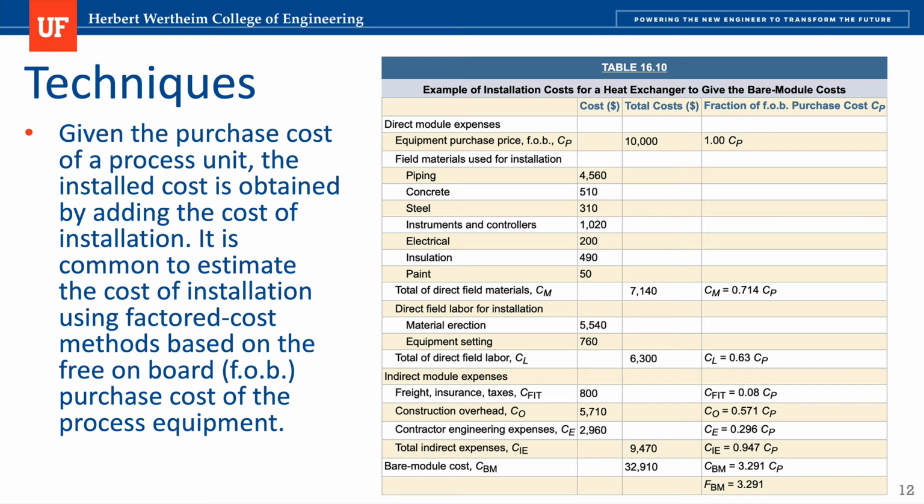So there are different techniques that you can use to calculate this fixed capital investment. Your book suggests a method that you can use. I'm going to be presenting one that is based on Turton's book. The reason why we're using that method is that we're going to be using a software called Capcost that is going to help you to generate what we call cash flow diagrams. And those cash flow diagrams can help us to calculate profitability.